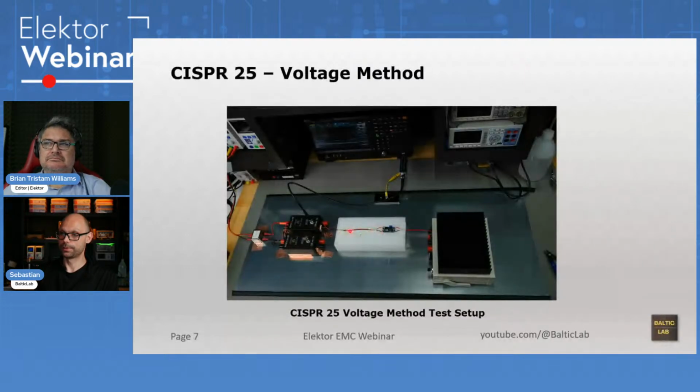Here, there's cable on some styrofoam. Here is the device under test, which in EMC is usually called equipment under test. Here is a passive load. Some people prefer to use resistors and solder them directly on there, but here I'm using the luxury of a passive load. All of that is mounted on a metal plate.